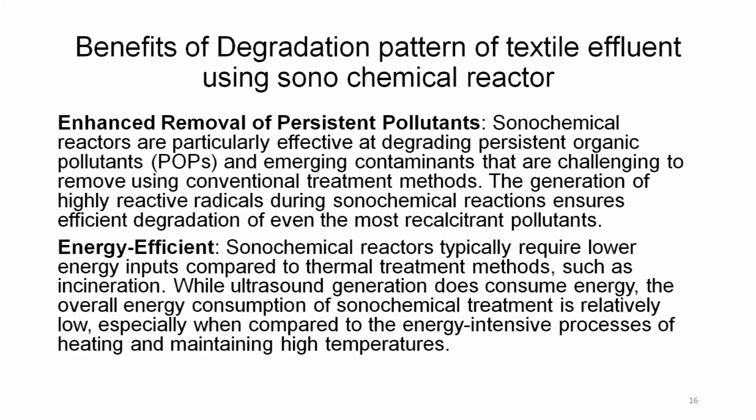Enhanced removal of persistent pollutants. Sonochemical reactors are particularly effective at degrading persistent organic pollutants, that is the POPs, which are very tough to degrade by other methods, and emerging contaminants that are challenging to remove using conventional treatment methods. The generation of highly reactive radicals during the sonochemical reaction ensures efficient degradation of even the most recalcitrant pollutants. So, even the toughest of tough persistent organic pollutants can be broken down by these very powerful hydroxyl radicals created by the sonochemical reactor using the ultrasound waves.